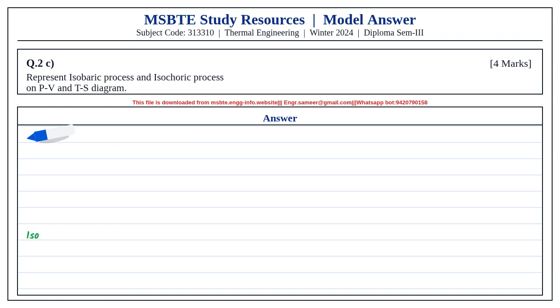Question 4b. Determine the rate of heat flow through a composite boiler wall. Given thickness of steel is 0.02 meter, thickness of insulation is 0.005 meter, thermal conductivities are 58 and 0.116 watt per meter Kelvin, and temperature difference is 250 degrees Celsius. For composite wall, heat flow per square meter area is temperature difference divided by total thermal resistance.